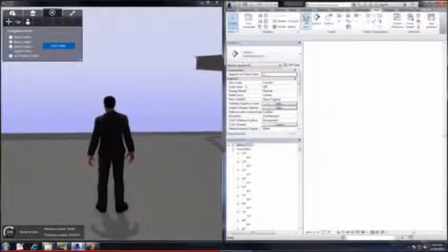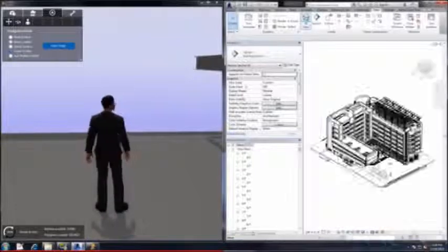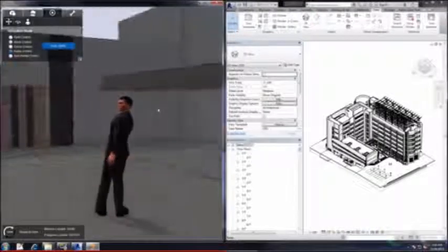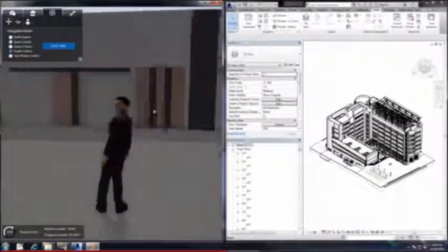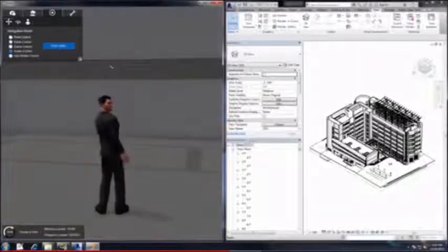So to bring all of that geometry back, just go ahead to the 3D view inside of Revit, and this will actually bring back the entire building inside of Fuzor. So any geometry that's removed by changing to a different kind of section view or floor plan view can be brought back by going to the 3D views.